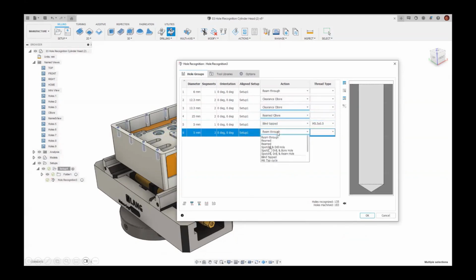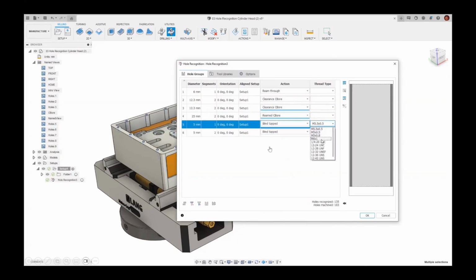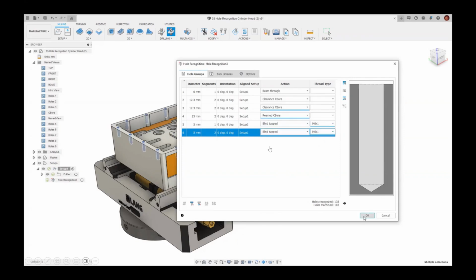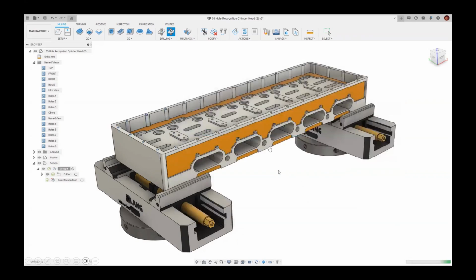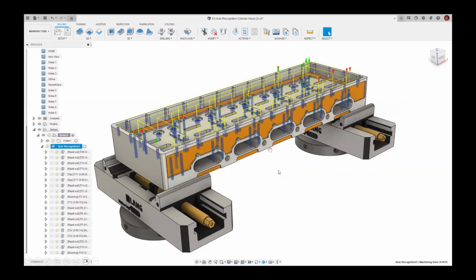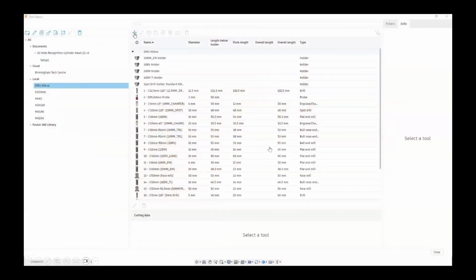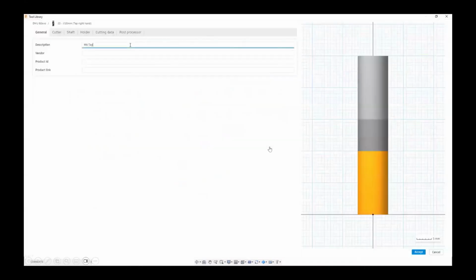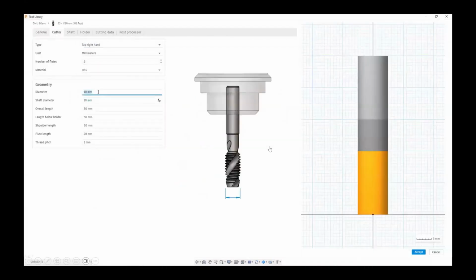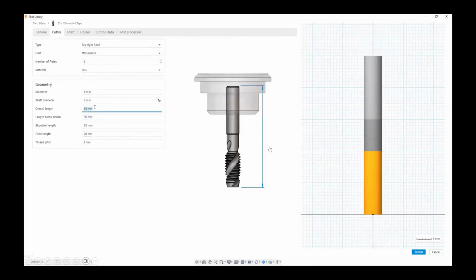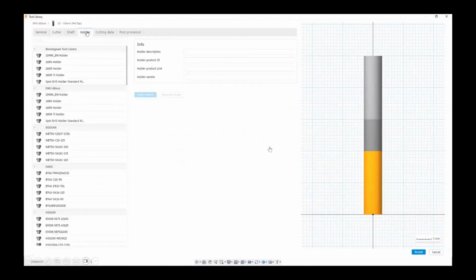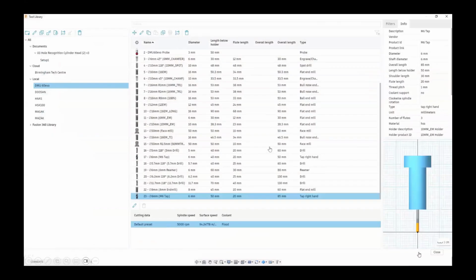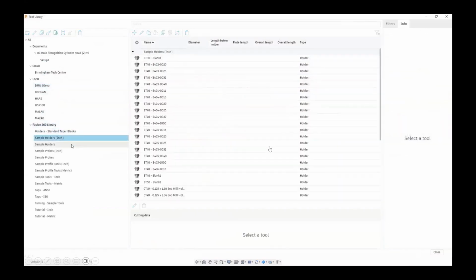And when you get to know exactly what types of holes are there, you can go ahead and select a template which you might have created or the process which you want, and within minutes, within seconds, it will create the complete drilling toolpath for you. Now, this works really well if you want to do it for multiple axes as well, and it can also identify from which axis would be the better approach for the hole. You can also select your own tool libraries in this.